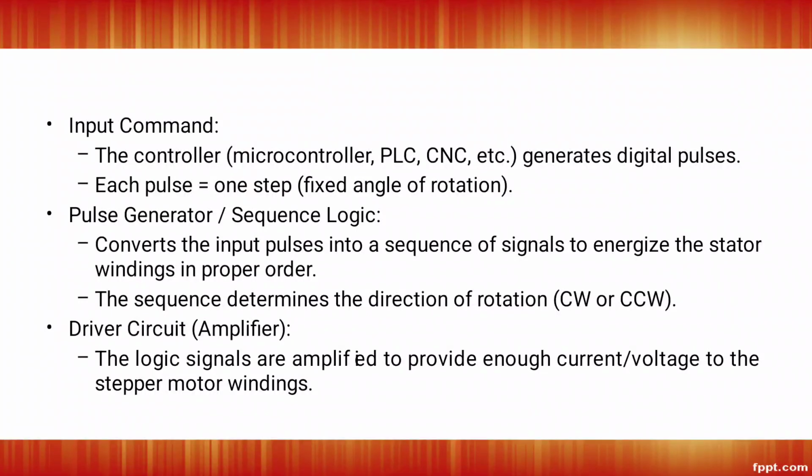So input command: the controller generates digital pulses. The pulse generator converts the input pulses into a sequence of signals. That is the main feature of a stepper motor. The sequence of signals energizes the stator windings in proper order. Next is a driver circuit or amplifier. The logic signals are amplified to provide enough current or voltage to the stepper motor winding.